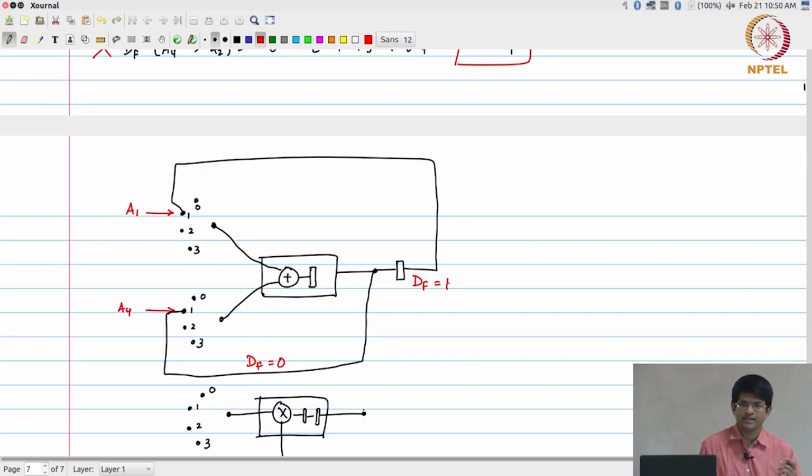Once they are given to you, you can then go ahead and calculate all the df values, and once you have the df values, you can then just basically say, okay, at time instant 1, the adder was supposed to execute this particular operation A2. Where did it get its inputs from? From A1 and A4. A1 and A4 are both outputs of the adder. What are the df values for that? For A1 it is 1, therefore put one register and take the output. For A4 it is 0, so directly take the output of this pipelined adder and feed it back to time instant 1.